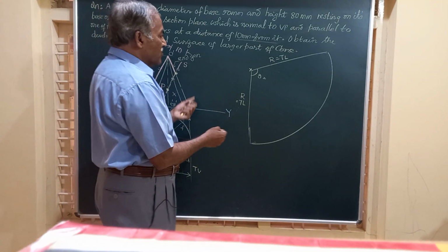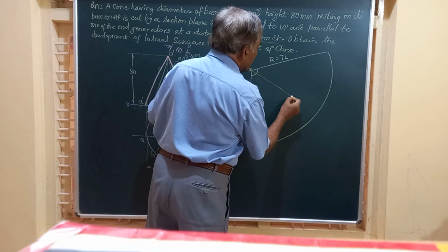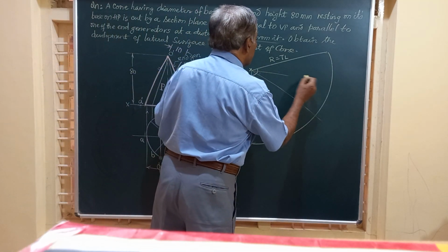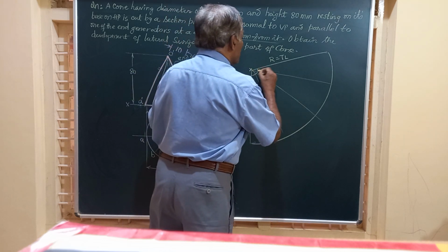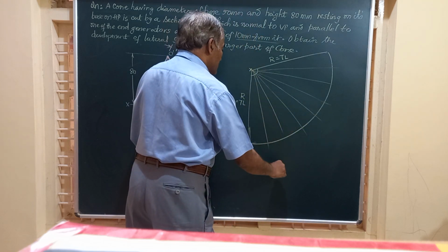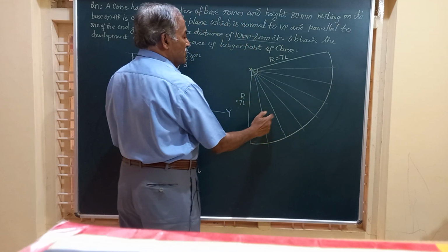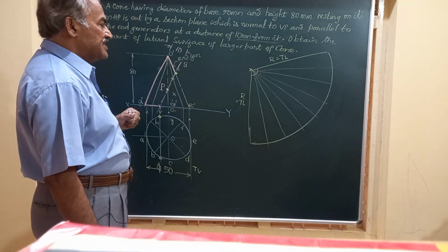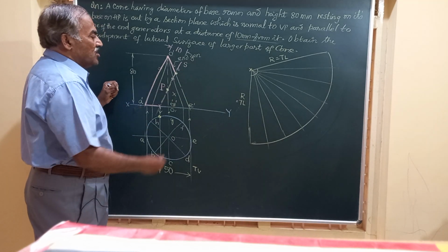And the angle you have got, this sector is to be divided into 8 equal parts, because the circle is divided into 8 parts. So 2 parts I have made, then again 2 more parts here. So this is to be further divided into 8 total number of parts. You can just count here: 1, 2, 3, 4, 5, 6, 7, 8. Now, after getting that theta and the development without section plane, let us see how to mark this.